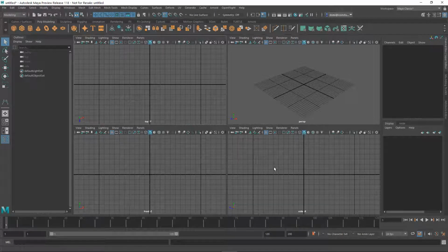The first image I'm going to bring in is in my side view. So I'm going to go down here to the lower right, and you can always look, it always has a label for what your camera view is. That's for your perspective window. This is your side view, which goes along your x-axis, front view along z, and top on y. So I'm going to click into that window and hit the spacebar so it zooms out.